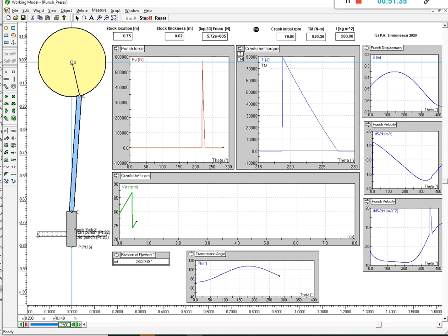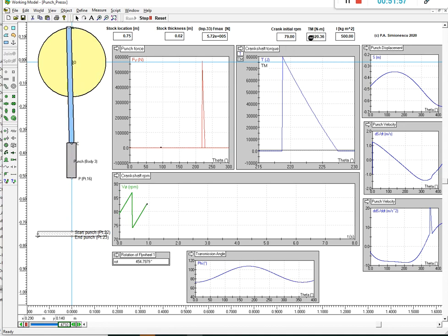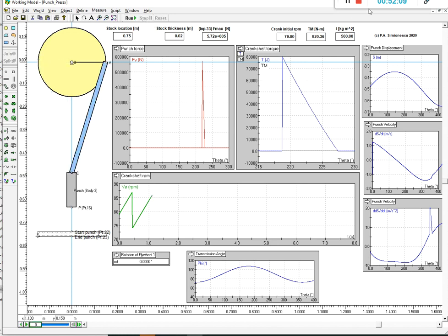of inertia. The other value, the calculated mean crank torque, is going to determine whether the zigzagging maintains the same boundaries, or, for too big an average torque, the zigzagging will drift up. For a smaller value, it means I don't have enough energy from the electric motor, so I'm going to slow down until it actually starts moving in reverse. Okay, so I need to stop here. I'm paused.